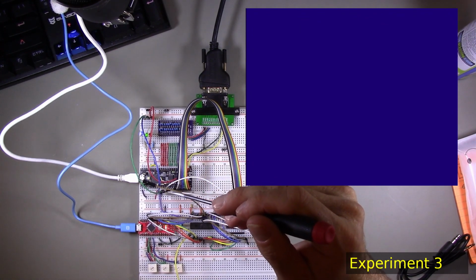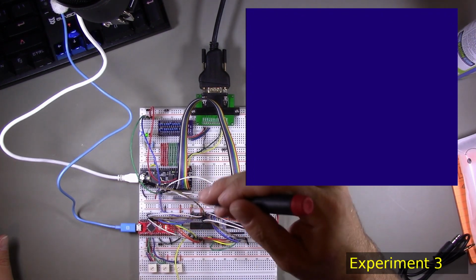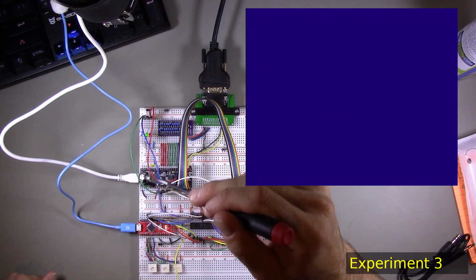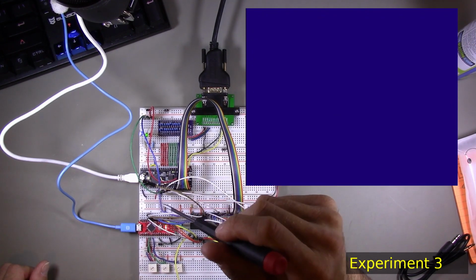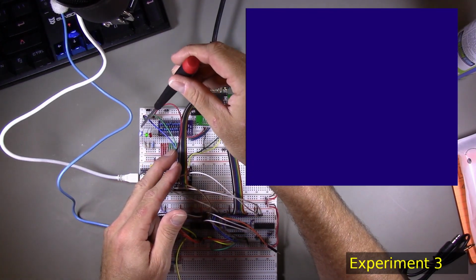Basically, the signaling to let the consumer know when a byte of data was available was not correct, and was flagging data as being available twice for each byte that was received. Interestingly, the way I figured this out was by adding some debug LEDs. You can see them right here.